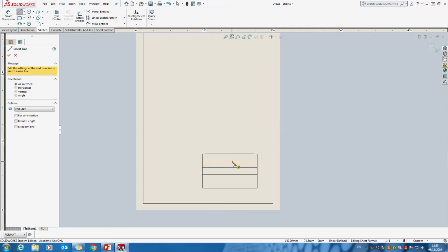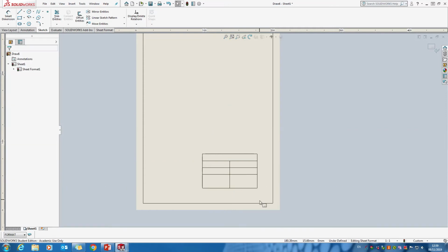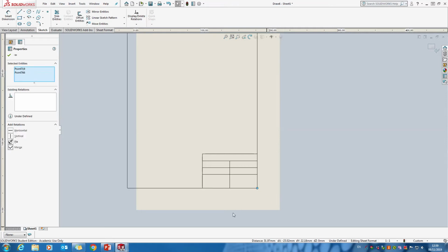After that, then we want a vertical division. So I go snap to the center point and draw in our vertical line there. Okay. So a common mistake people make, and I'm going to show you here now, is when they hold control and hit the 2 corner points, the border will move up to the title box instead of the other way around.